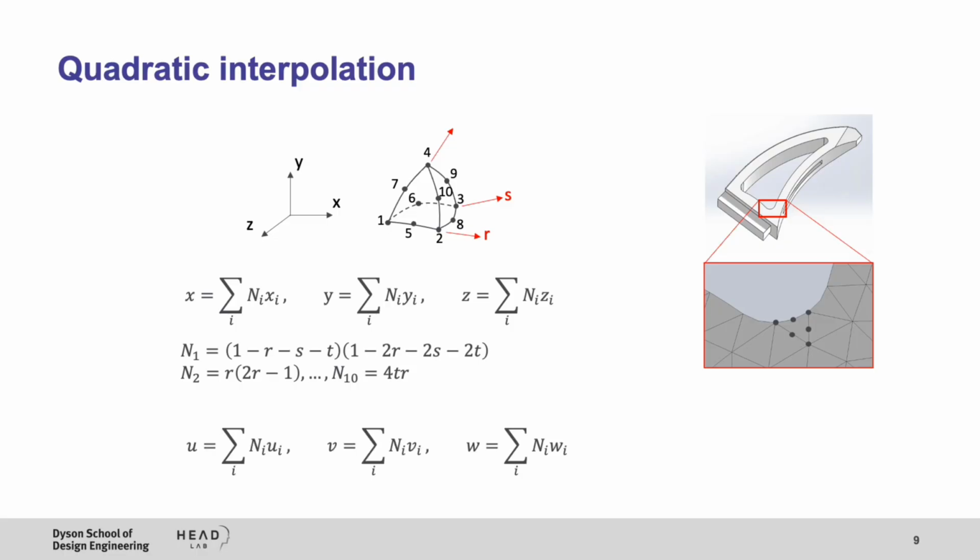Again, for this element we use the same shape functions to interpolate the geometry and the field variable, which is translations in our solid mechanics problem. We can use matrix convention to write the displacement vector in terms of the shape functions and vector of nodal displacements.